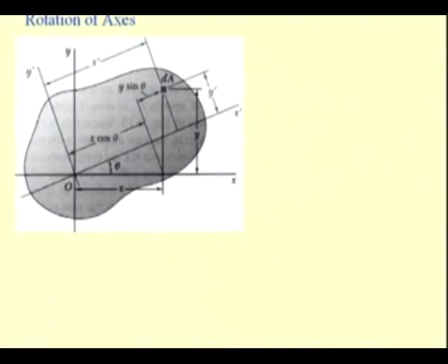So, we have this axis O x y and this differential element dA. The product of inertia and the second moments of inertia of this area with respect to this axis are known, like we have the second moment of this area dA with respect to OX as y square dA, and when we integrate it we get the second moment for this complete area.